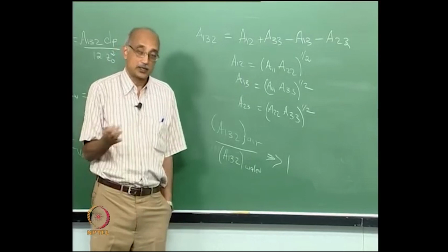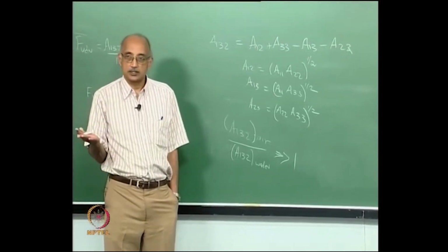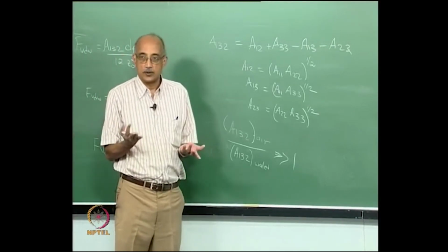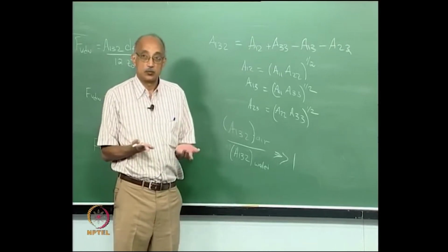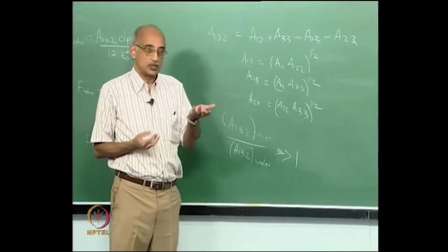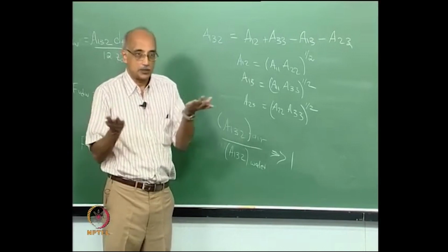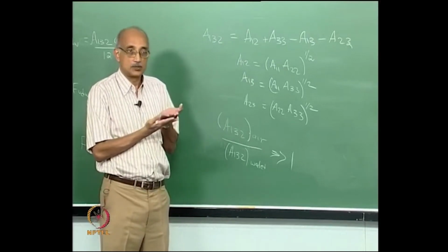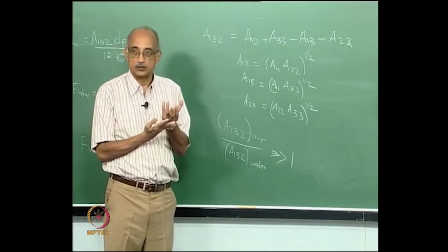Now, does that have practical implications? I think you all know from your everyday experience that it's easier to wash dishes, for example, when you have soaked them in water, right? Why is that? One reason is that as soon as you take this dry interface between food particles or dust particles and a plate or some other solid surface, the Hamaker constants are very high. So the food material is strongly adhered to the surface.